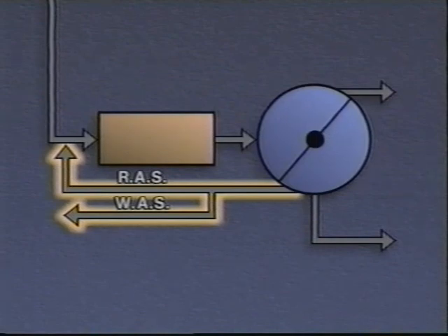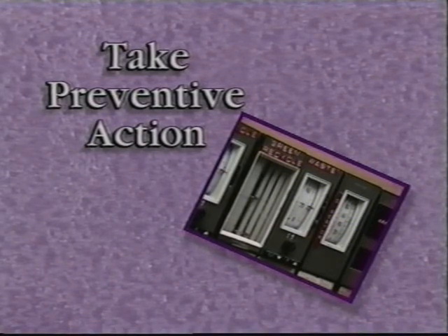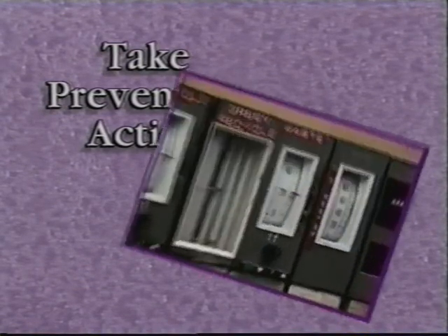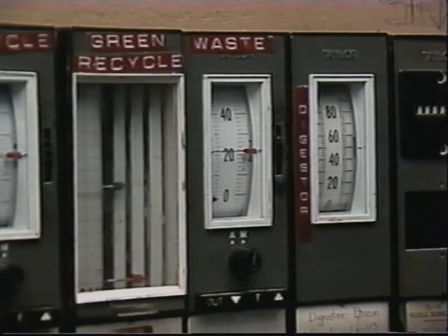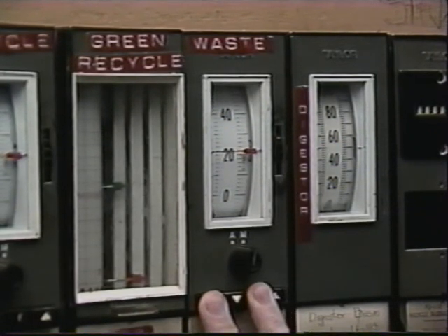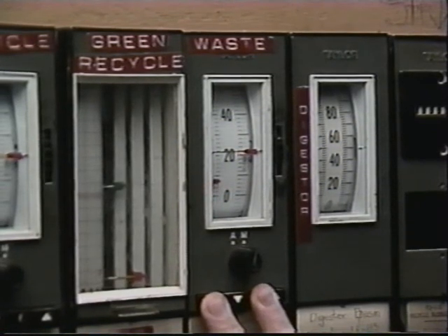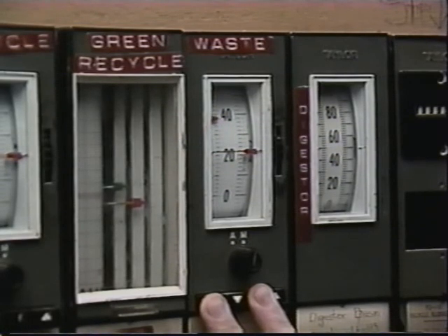In fact, a high sludge blanket level is often caused by insufficient recycling or wasting, but the rates are found to be normal in this case. The recycling and wasting rates are okay for normal conditions, but since there's a high sludge blanket level in the secondary clarifier, the amount of waste activated sludge that's removed may have to be increased to bring the level down. Adjusting the recycling and wasting rates is a temporary preventive step that can take care of the sludge level for the time being. But we still need to discover what caused the high level in the first place.